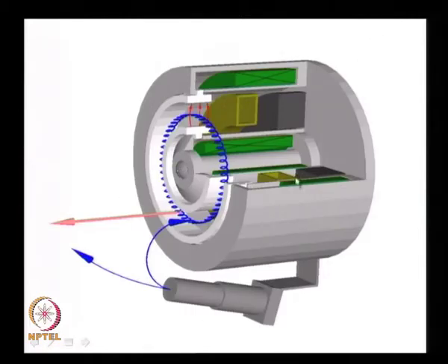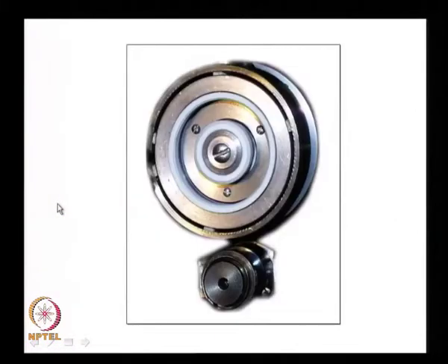Well, this is the picture of a Hall effect thruster. This is where the electrons are generated using a cathode. It enters the annular gap over here. There is a strong magnetic field in this particular gap, and therefore the electrons spiral, you have an anode here which pushes the thing out and you get the thrust over here. This is the phase view in the annular gap.